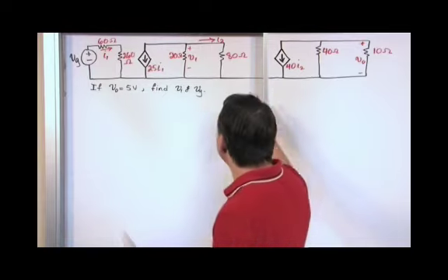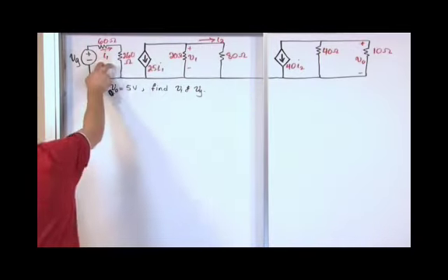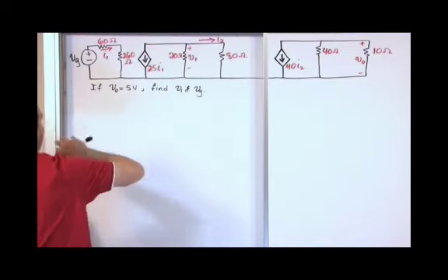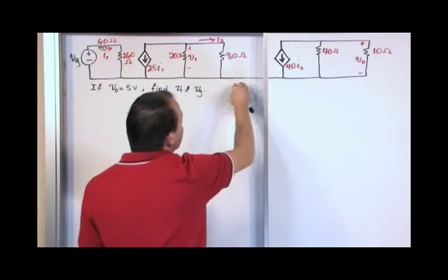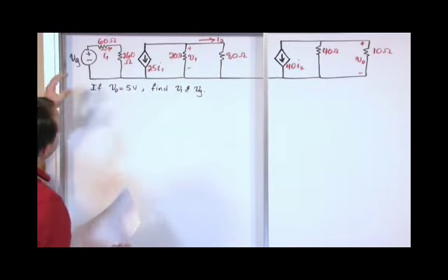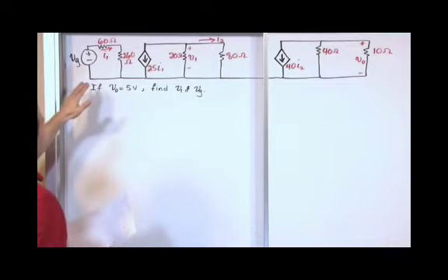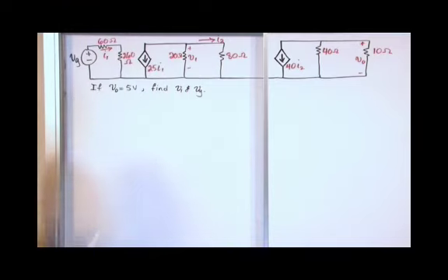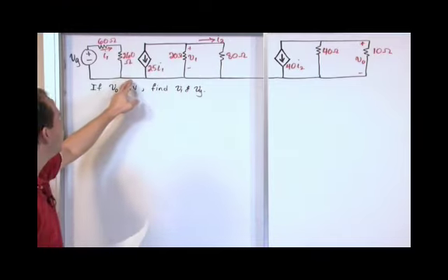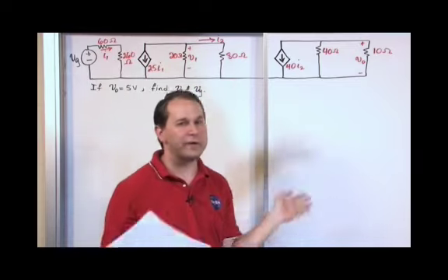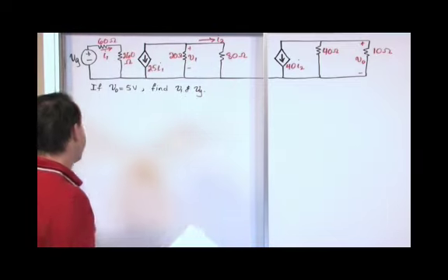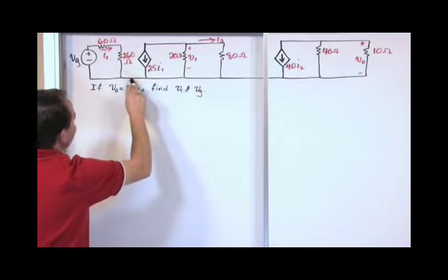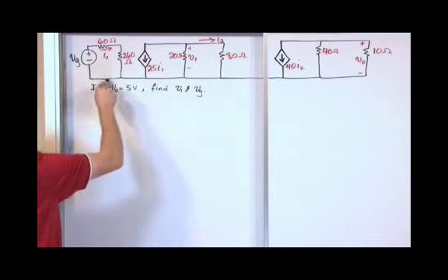So that's what is sort of trying to be illustrated here. You've got a circuit here, you've got a circuit here, and you've got a circuit here. These sources are really dependent on what's going on over here, but we've tied their low sides together so that the potential difference between the low side of their voltage between each of these circuits really is at the same place. So if you ever see a circuit like that that's got something tied together at the bottom, that's all that's really happening. It doesn't mean, this is what I thought when I first saw this years and years ago, that you've got current from this source going through this and doing something nuts and coming back. That's not what it means.